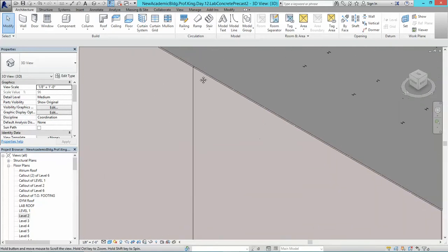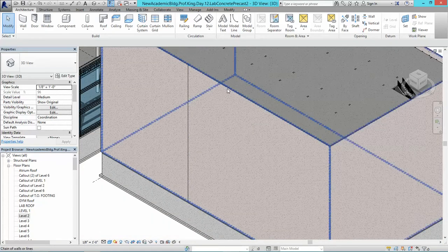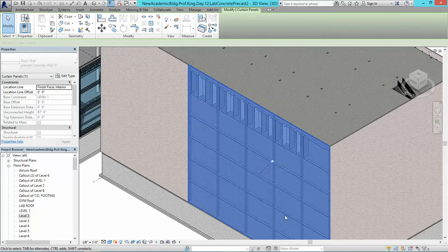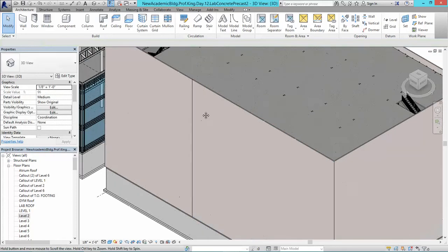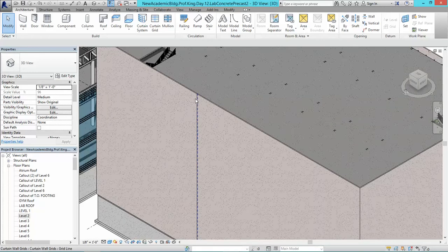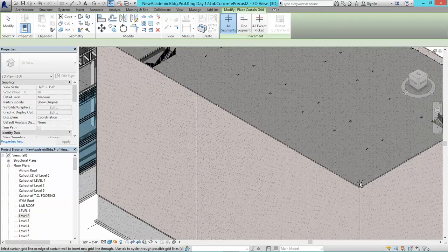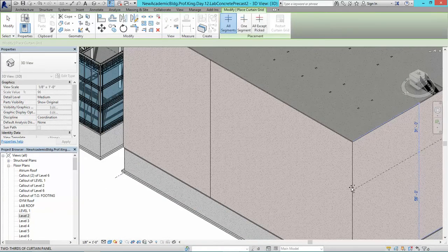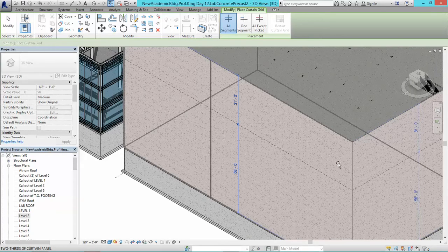So now by placing that line, I can tap into this particular panel and give it different qualities or different properties of materials and thickness, etc. So it's a very powerful tool. You can actually do totally different parts of the wall in different areas without needing to split, as in the other option. You can set curtain grids also horizontally by tabbing. There you go.